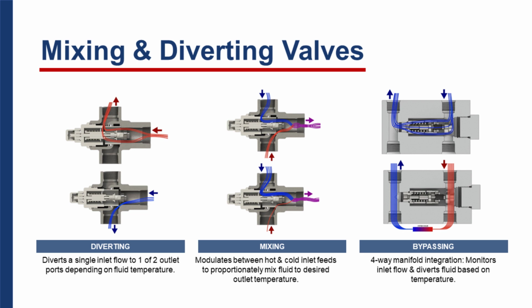But when it gets up to temperature, the cartridge style will close off that port and will have 100% of the flow go out through the heat exchanger or radiator and then back to the sump.